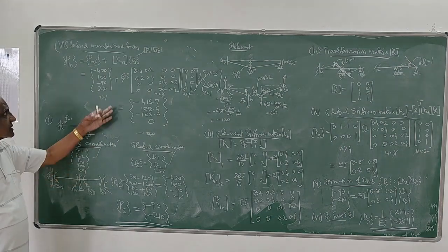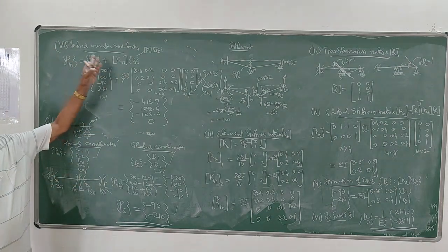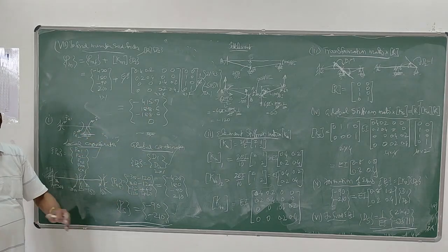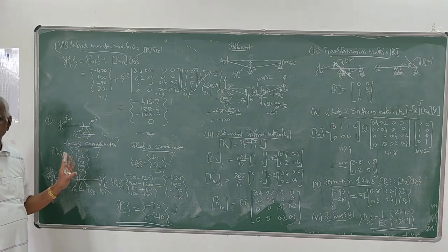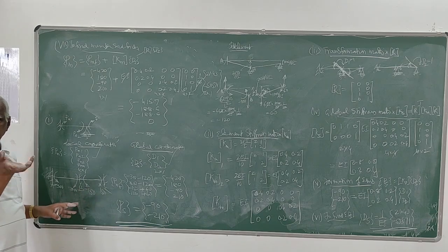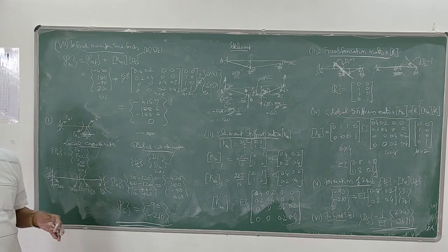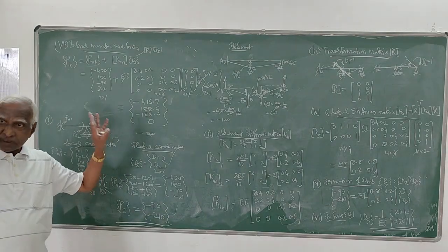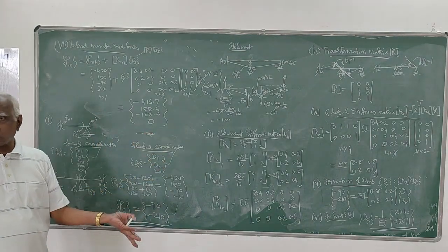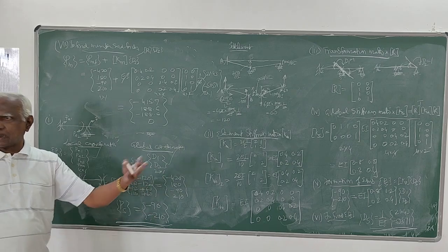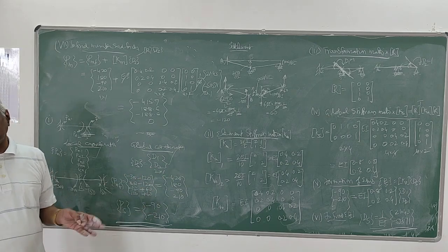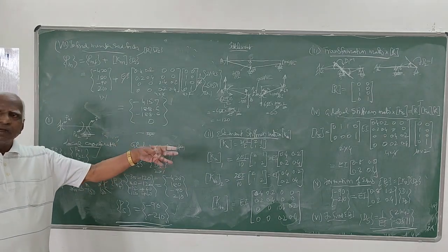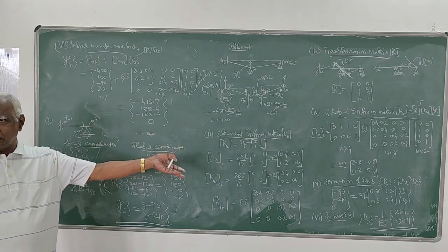There are other matrices, they are all the same. The formula for finding final moments and everything, even the data, that's also just a name change. First step is common for both. You have to name the joints, name the members, mark the coordinate axis, and mark what is unknown to be determined. That has to be the same, whatever the procedure, classical or finite element. Only Km deflection, of course, that also has to be the same.